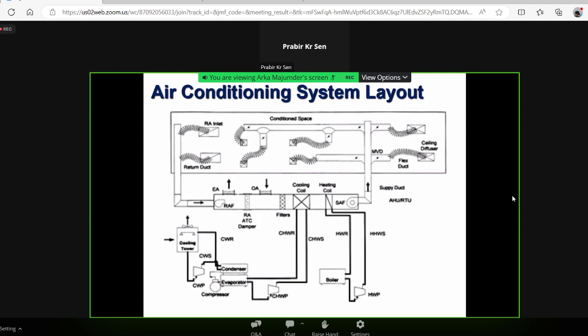So we supply the water in the cooling coil where we cool the return air taken back from the room. You can see on the top there is a room. So we are taking the return air back from the room, and we flow it over the cooling coil, recool it, and supply it back to the room. And the chilled water gets a little warm. We take it back by the chilled water pump, pass it through the evaporator again, recool it and resend it.